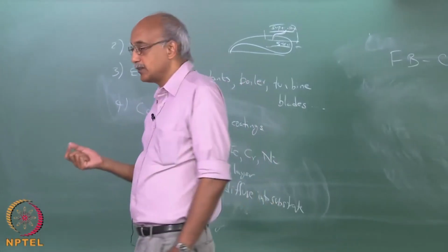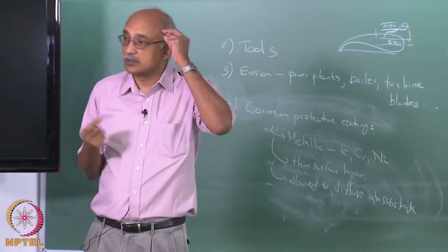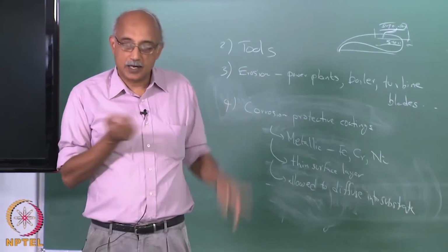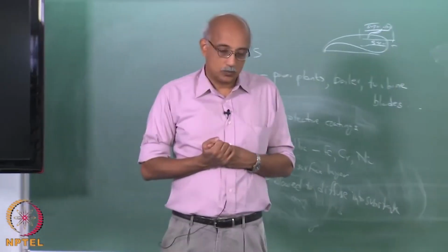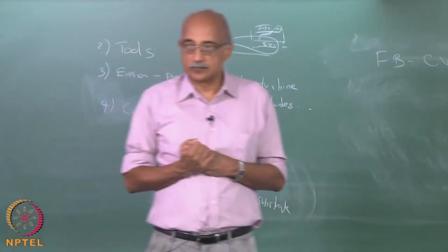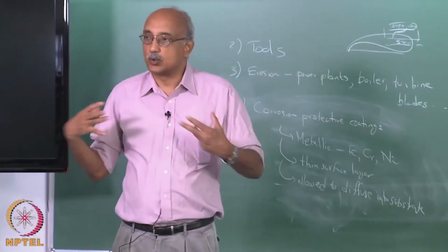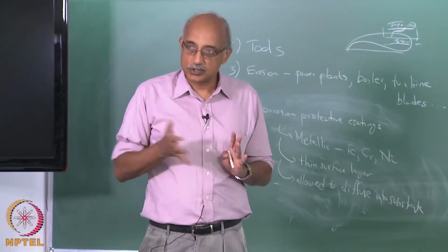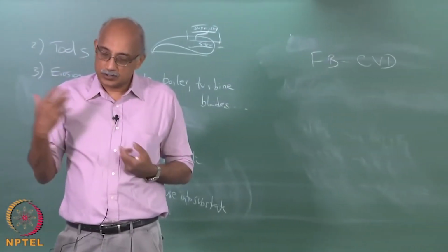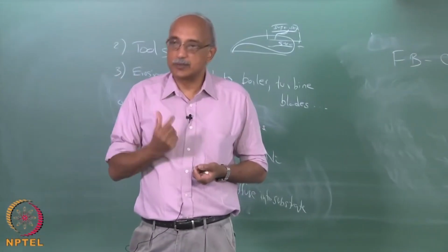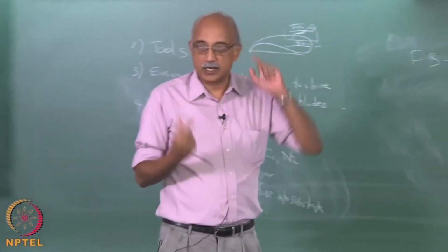For example, in many applications that involve electronic components, electrostatic discharge can kill the device. So, you have to provide a static dissipative kind of environment for manufacturing, and one of the places where static discharge can happen is the human body, particularly the clothes, because that is where static forces can build up. So, what they do is these garments, they actually put down some coating on the fibers that are used in these garments to improve the conductivity, and therefore make it difficult for static charge to build up.